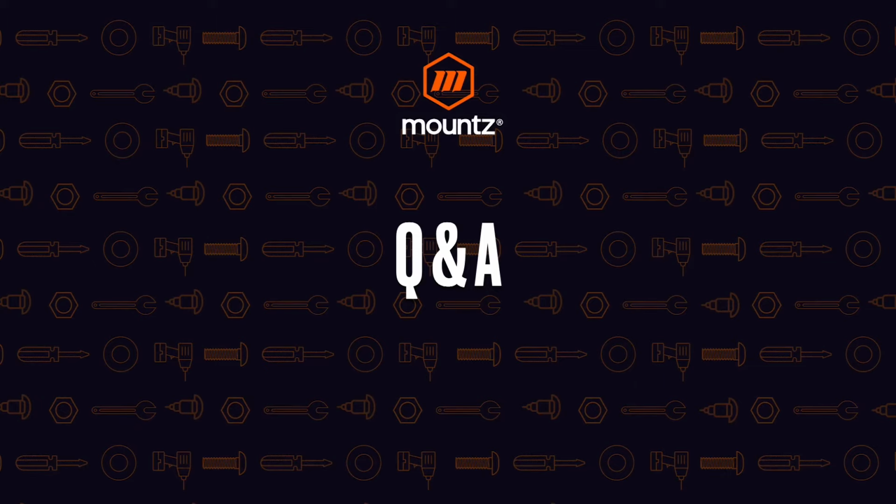Morning, Dave. One of the questions we have is, what is the difference between a transducerized and a non-transducerized tool? So the basic difference is that a DC tool can come in two different types of tooling. The transducerized tool has a sensor that is built into it that is allowing it to monitor the torque value from that tool. And then that tool is basically being controlled by that sensor and giving us that ability to read the actual torque output.